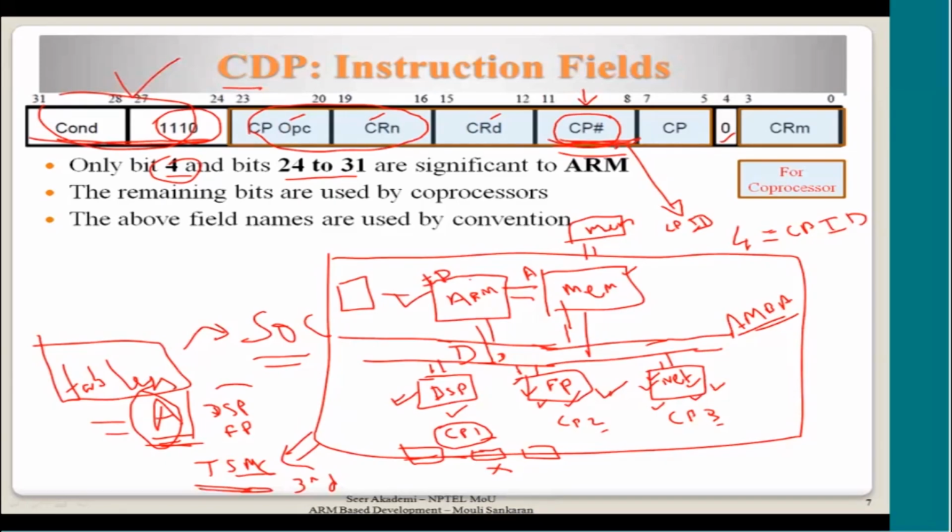I may have internally maybe only 8 registers. In that case, though ARM provides me a 4-bit pattern for each operand, I can restrict it to a 3-bit pattern. And I may have multiple operations to be performed inside the processor, so I cannot encode them in this limited 4-bit pattern. I may need more bits for that. So it is completely implementation dependent how they interpret the remaining part. We cannot say whether they will combine this and this, or in whatever order they do, it doesn't matter.